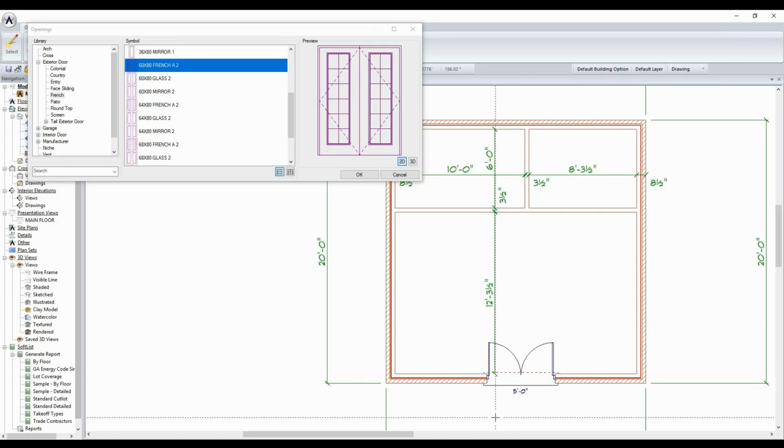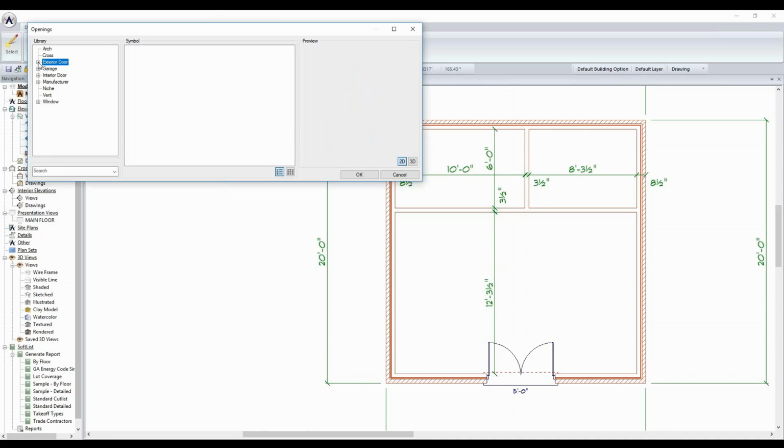Here again, we're just sketching. We've got the box close to what we want, which is helpful. So when I'm adding walls, I'm not going to overrun other walls when I start moving them around. But when I'm adding the openings now, I just have to sketch them in where I think I might want to put them. So that's the only exterior door we're going to put in. I'm going to close that one up and go to interior doors.